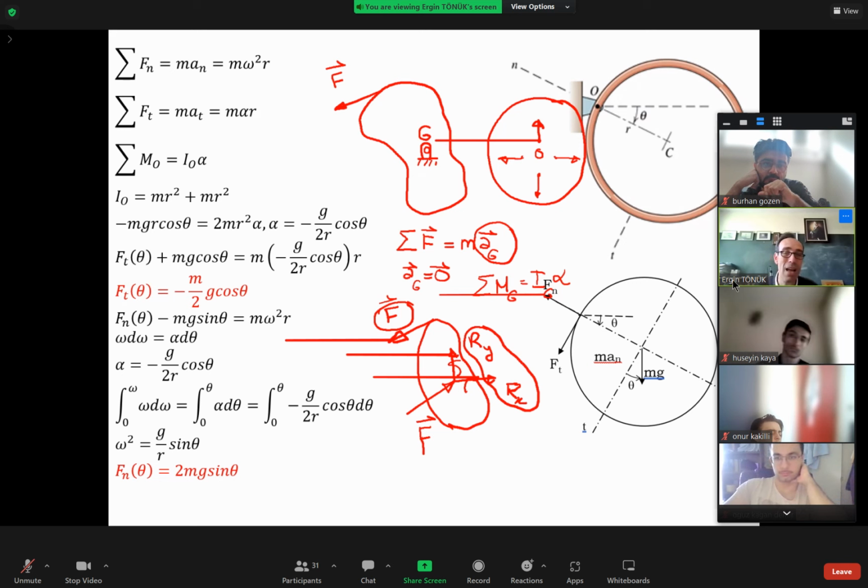But if it's inaccurate equipment, say a few millimeters, then you might feel the unbalance at speeds exceeding 100 or 120 kilometers per hour. So you can't do anything exact. You can't bring it exactly to that point. That's not possible in practical life. On computer simulations, you can enter the numbers exactly, but in real life, in every measurement, you have tolerances.